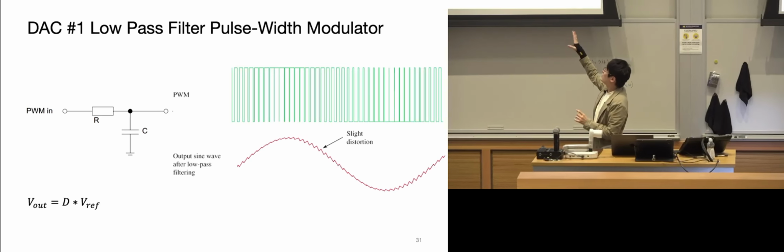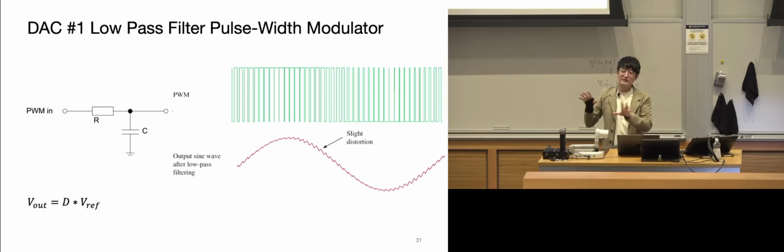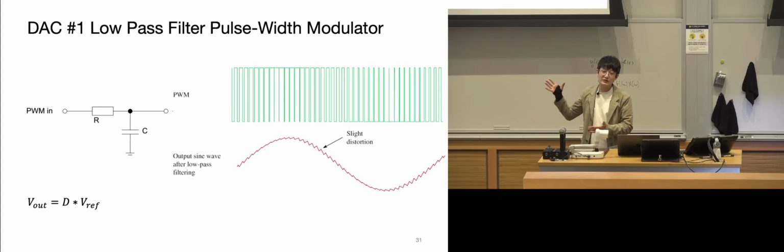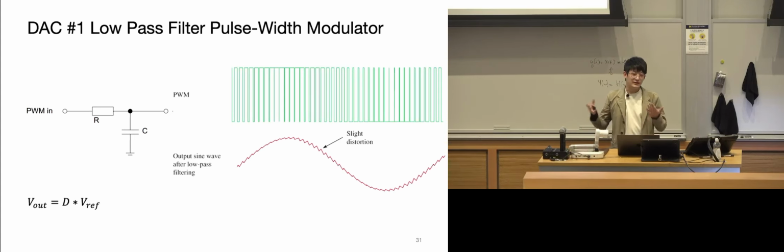This obviously is a zoomed in version. In the actual wave, it will look reasonably okay. It depends on how fast you set your PWM signal. The faster it is, the smoother it is.